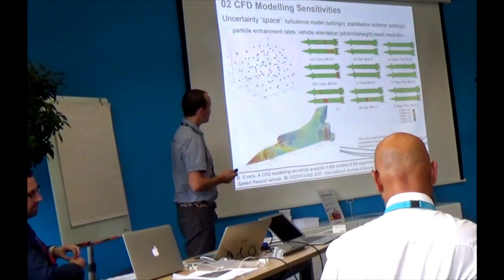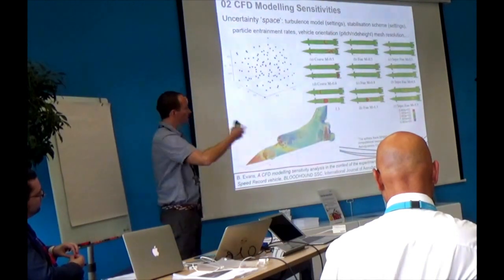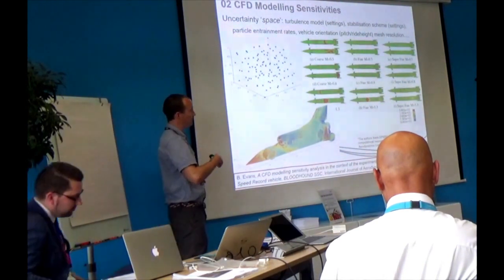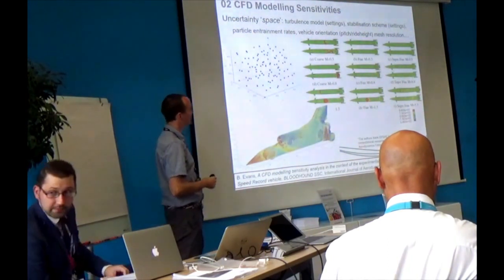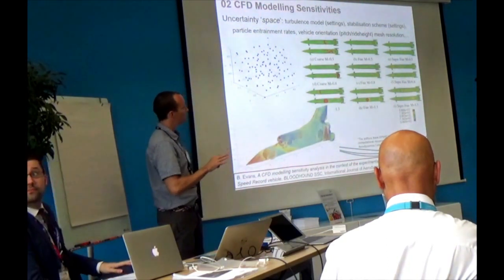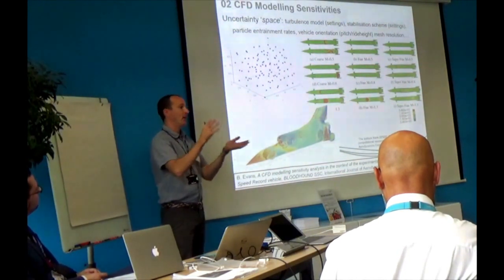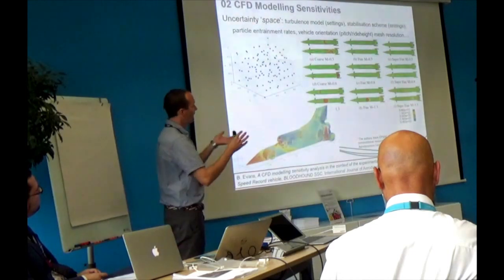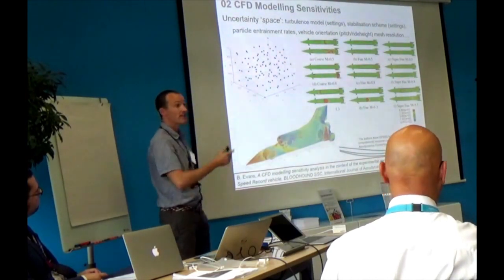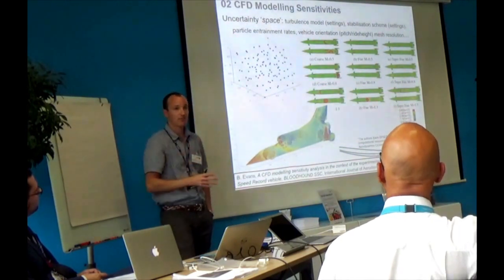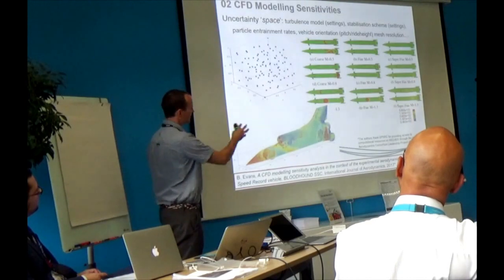So the clustering of the pressure sensors, and there are 250 sensors across the surface of the car, we'll start getting data from in October, and then meaningful data at high speed next year, are all clustered around regions where, in simplistic terms, the standard deviation in our modelling results is the largest, i.e. we have the largest uncertainty. It's a pretty pragmatic approach, but that's the approach we've used in terms of how we cluster these sensors.